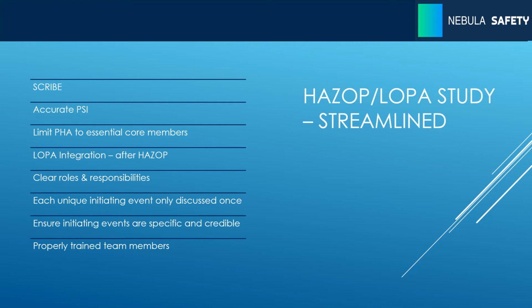I cannot emphasize enough how much accurate PSI makes a difference during the PHA study, especially when it comes to P&IDs. We do spend a lot of time redlining, but what really derails our studies is when operations will come in and say, look, this is not how it looks in the field. We changed that 3 years ago. And then I actually have to send them with the engineer out in the field and have them redline. We typically will lose a day or two off of that.